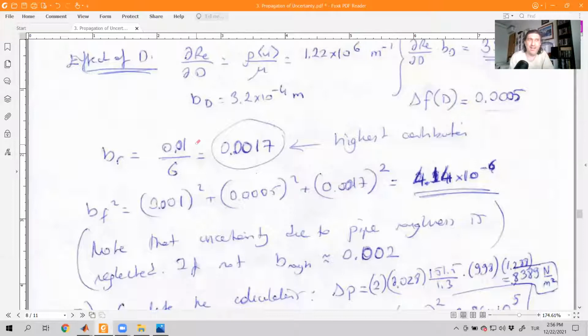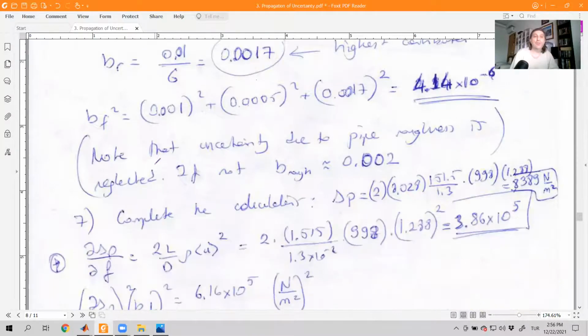But there is going to be an uncertainty related with that reading. I'm pretty sure of that, because it is logarithmic and also it doesn't have units. So when you use a ruler, there are going to be some uncertainties. Anyway, we have found the uncertainty related with fanning friction factor using this method. What I basically did is look at my x-axis. My y-axis is fanning friction factor. Whatever the x-axis is, if fanning friction factor in that graph depended on velocity, then I would have only taken the partial derivative with respect to velocity and done the calculation. That would be pretty easy.